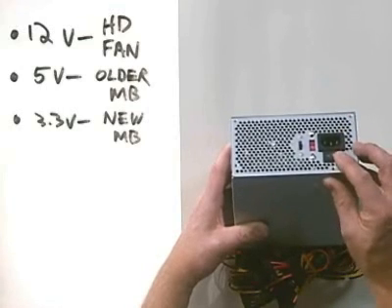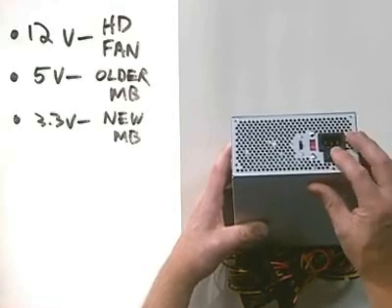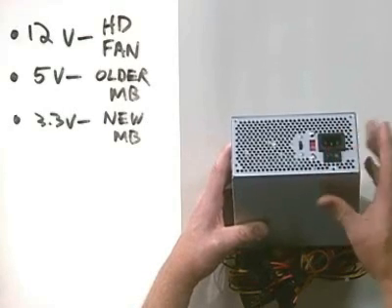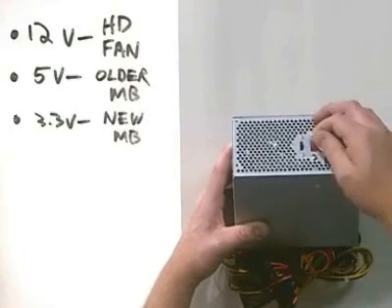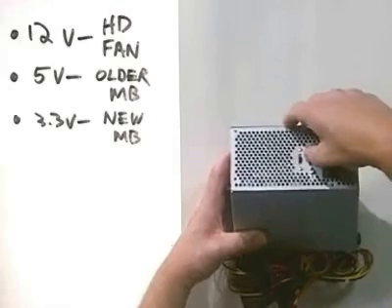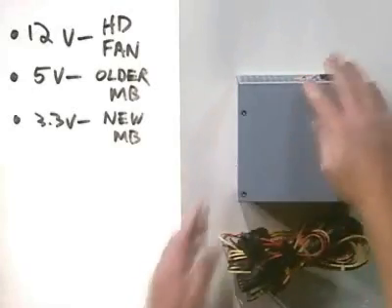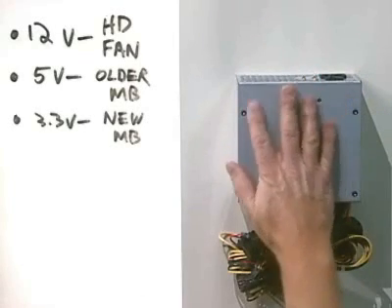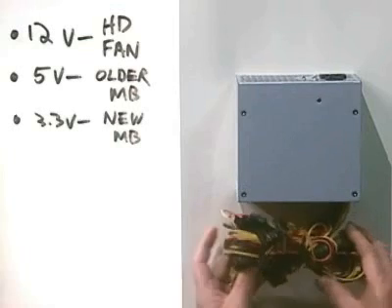Got a switch right here that allows you to turn the power from the wall off or on, turns the power supply itself off and on. And there's a switch over here that allows you to change whether you're using 115 volt or 230 volt current. The electrical current, the AC current, comes in through that socket, goes through the power supply, and is converted into DC current, which comes out on this end of the power supply.